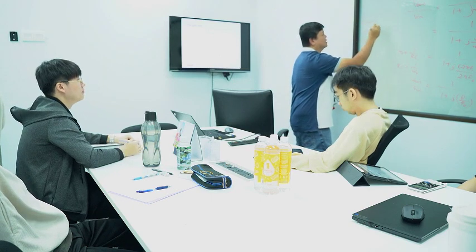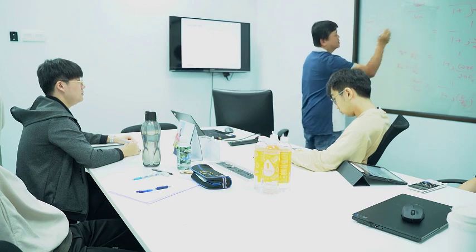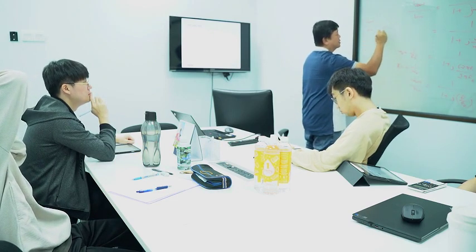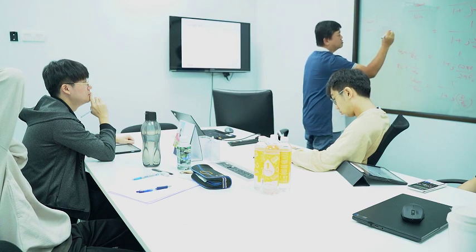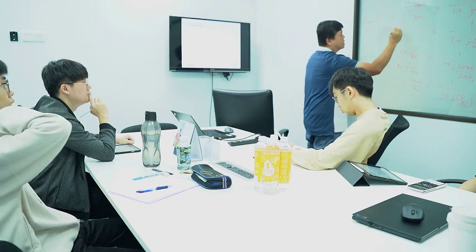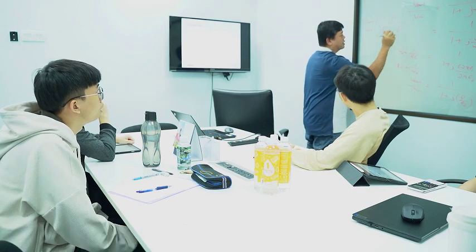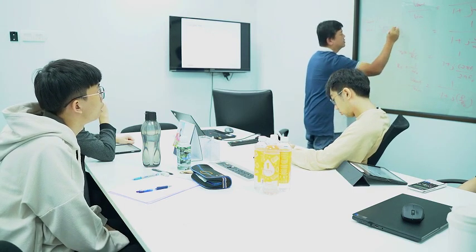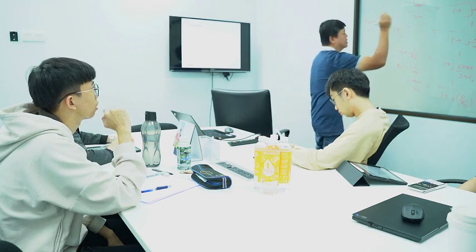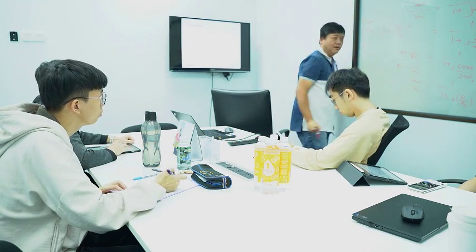So this one becomes the square root of 1 squared plus, and then this one becomes not j anymore, f divided by f0, squared. Correct? 1 squared plus that squared. Remember, a squared plus b squared. Remember the mathematics you did in university.